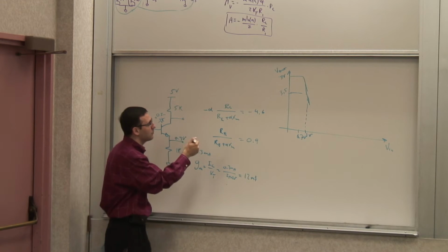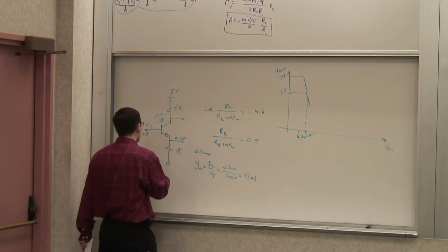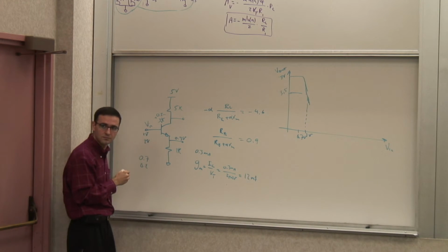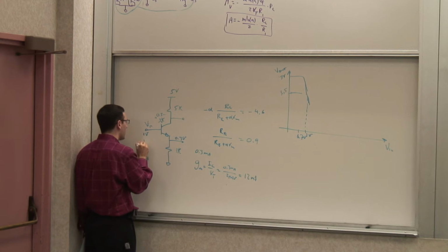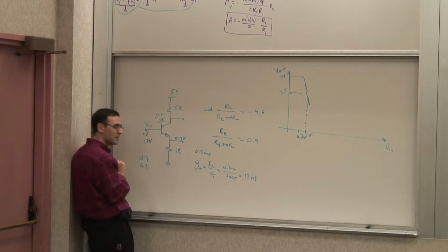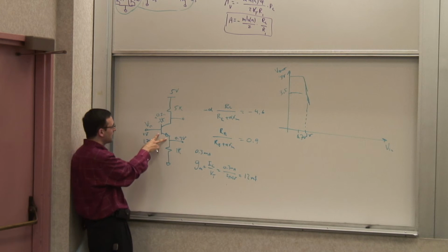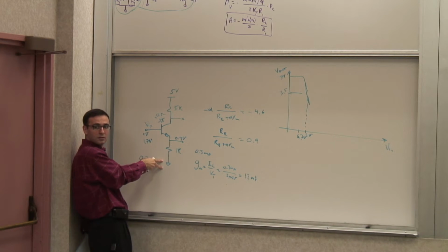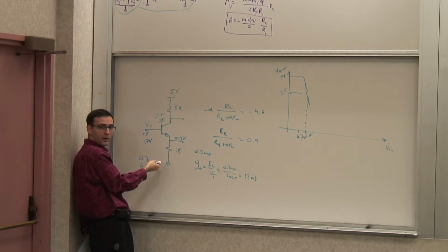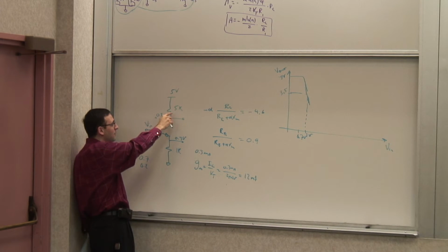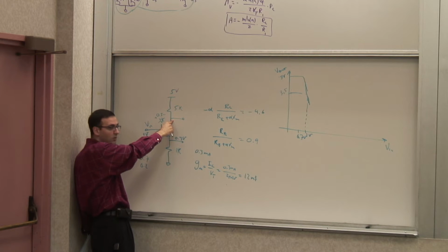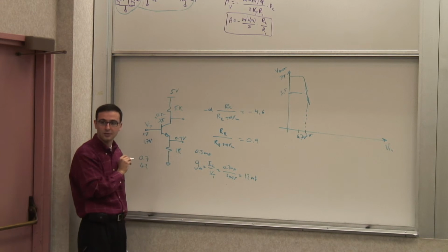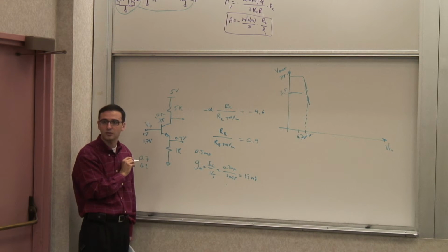Well, I know at 1 volt, the output is 3.5 volts. So if I raise it, let's say I go to 2 volts, just for the sake of argument. Well, let's make it something simple. Say 1.7 volts. At 1.7 volts, this is a 0.7 drop, this is 1 volt. What is this current? 1 milliamp. If the transistor was in the forward active region, this should be 1 milliamp. If it were 1 milliamp, what would this voltage be? 0. So it says it's down here, but that would be much lower than the 1.7 volts. So it has already saturated. So that can't be a valid point.